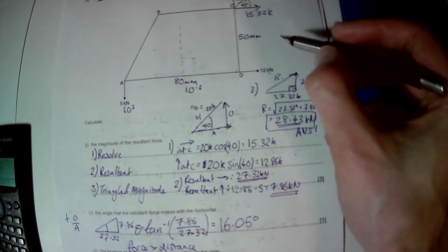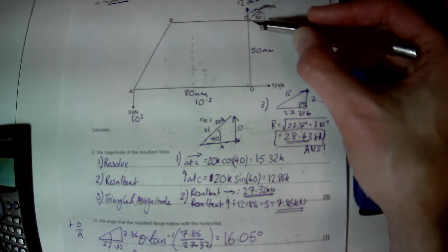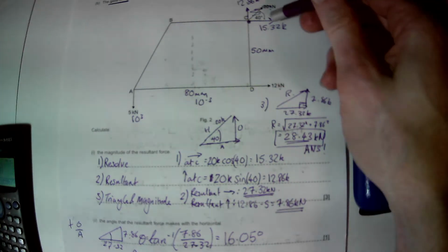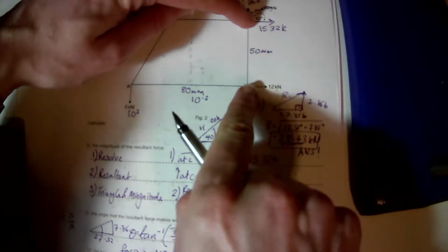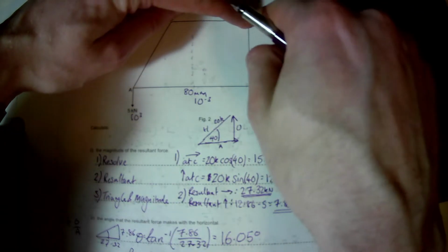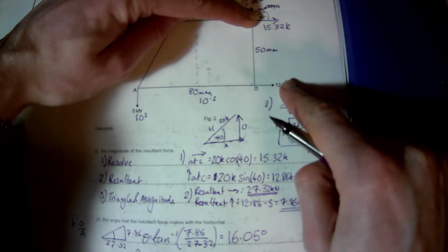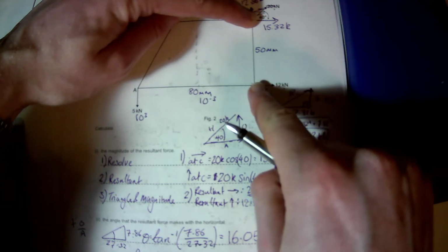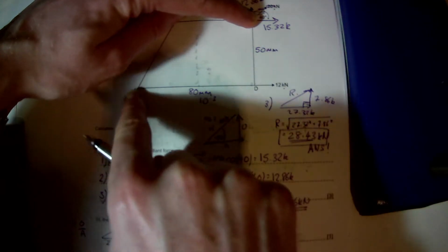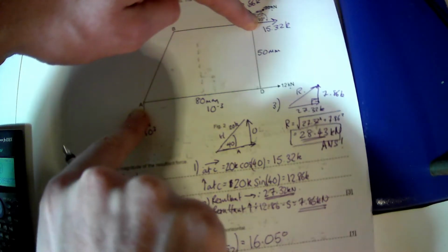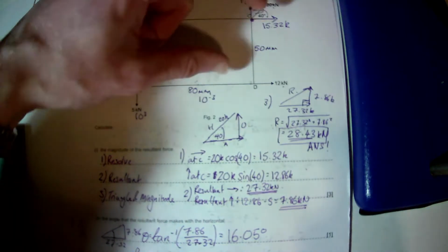Now, the moment at point C is the turning force exerted about this point. For the forces that have got a turning moment, if I put my finger there and I push in the direction of the forces, any force applied at C is not going to have a moment. However, this one at D is going to have a moment that is anti-clockwise, and A is going to have a moment that is anti-clockwise, because it makes it spin anti-clockwise when I push in the direction of the force. So the total moment